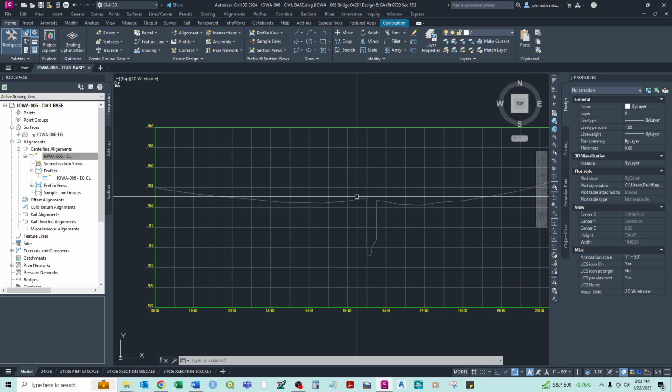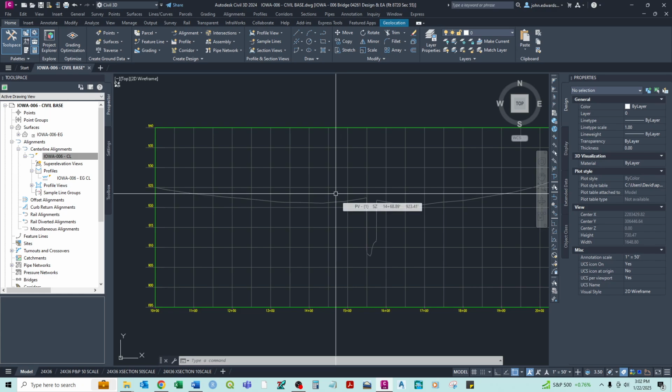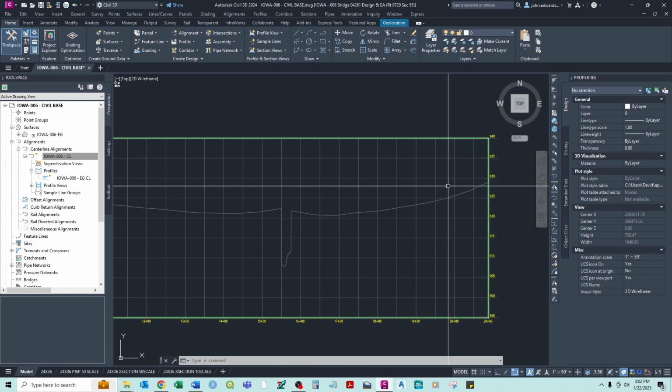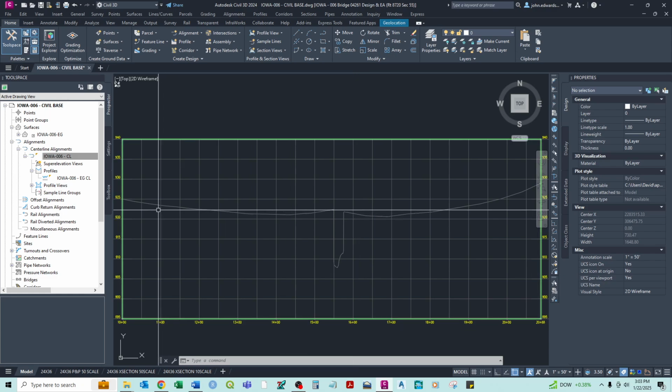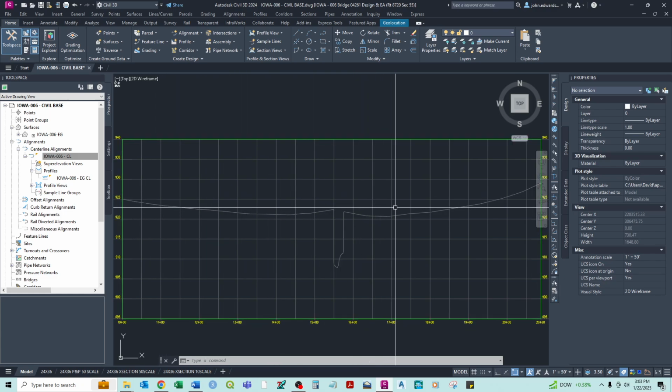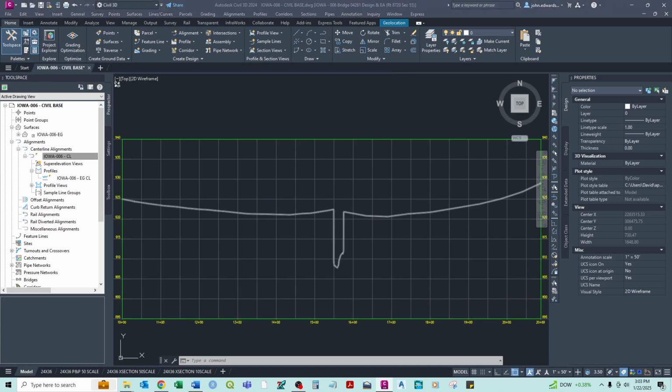For bridge replacements, a lot of times you may have to raise the roadway a little bit to meet hydraulic standards of overtopping and things like that. And for some of these smaller county roads, they may not be actually designed to the county standards or currently meet county standards. So you'll have to upgrade things like vertical curves, like tangents, to meet the standards in your design. So those are some of the things you'll have to fix. So what we want to do now is just throw in a basic roadway profile and be able to illustrate some of the ways to do that.